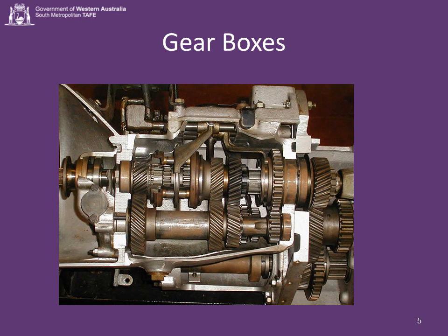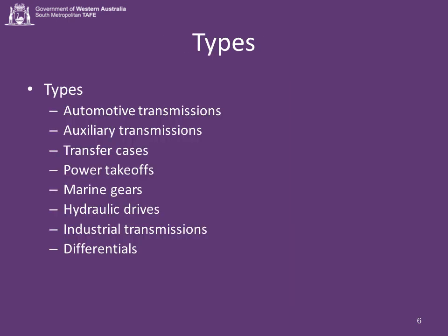They're durable, rugged and efficient, but are capable of only providing a specific number of fixed gear ratios, normally chosen for applications involving heavy load or requiring long, trouble-free life. Generally more expensive than belt or chain drives, gear drives are commonly classified according to their end use.